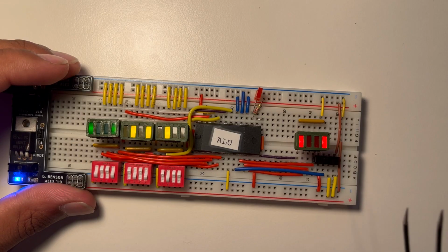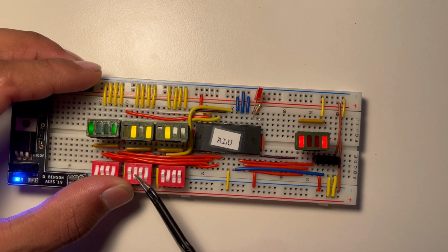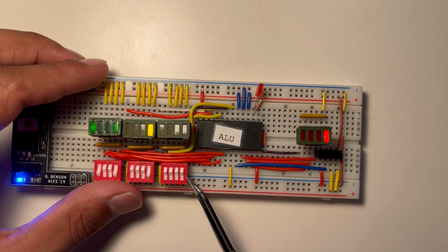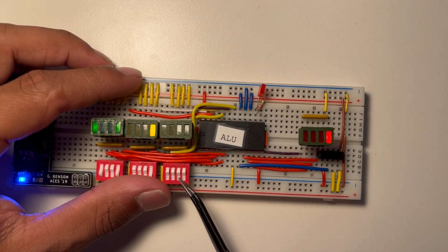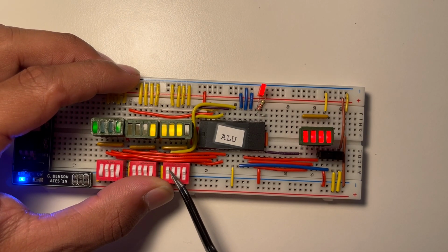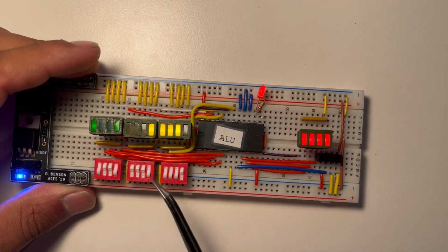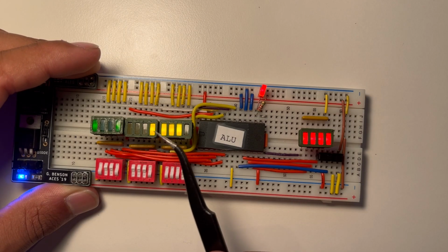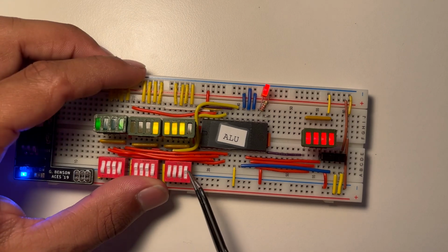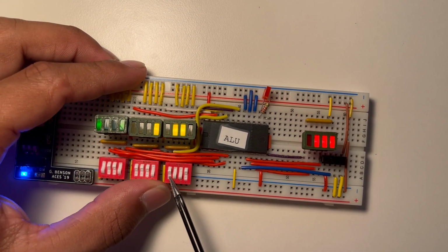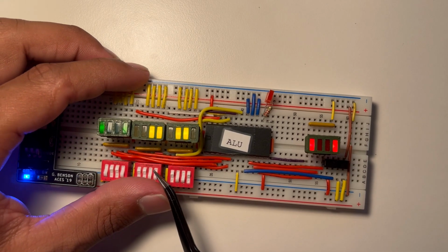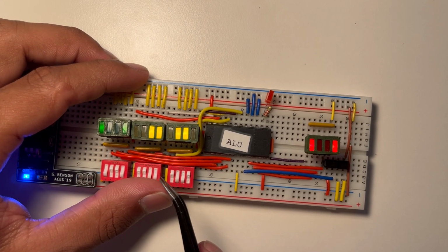The thing that I find interesting about the addition circuit is that if I set them all low, it almost behaves similar to an OR gate. At least it does when no 2 of the same bits are selected. So if we have this configuration, for example, you can say, oh yeah, that's OR, because it looks like it's just ORing the 2 bits. But then as soon as you flip 2 of the same bit, like for example, these 2, then it becomes different, but it's just a cool feature of the adder.